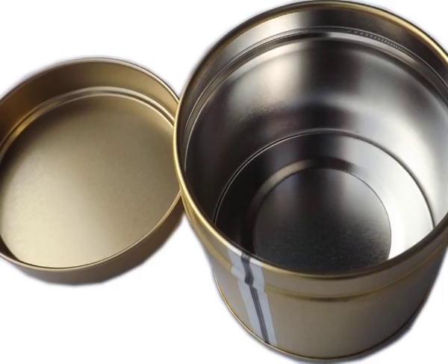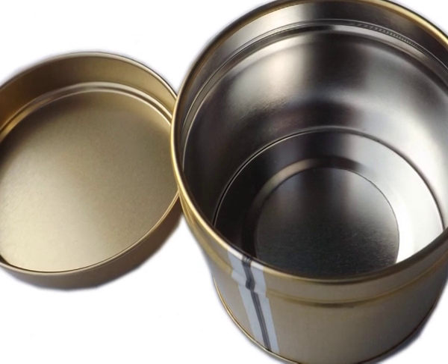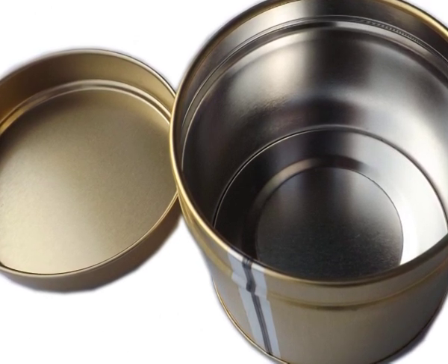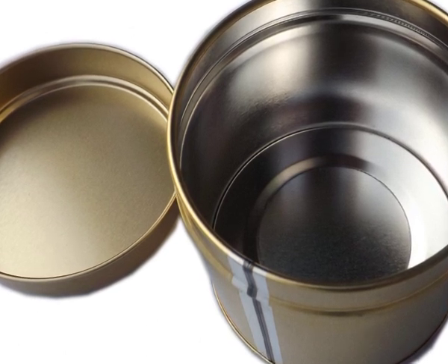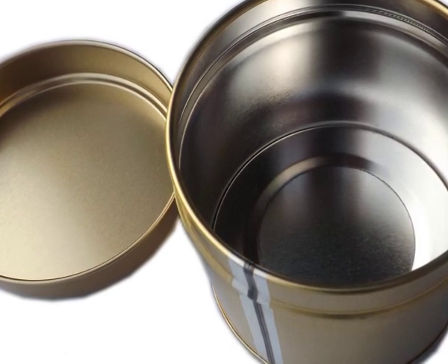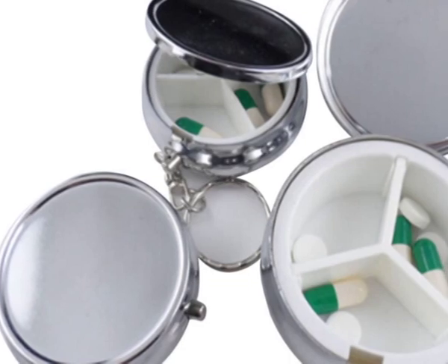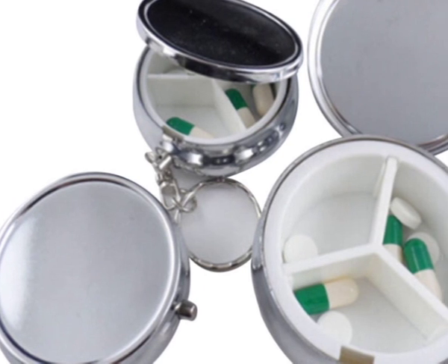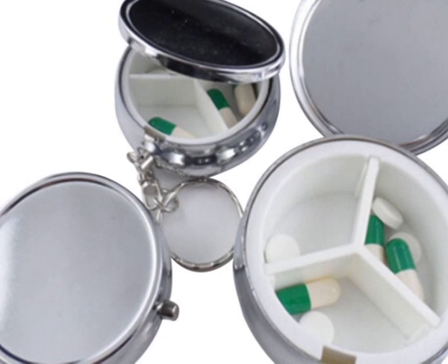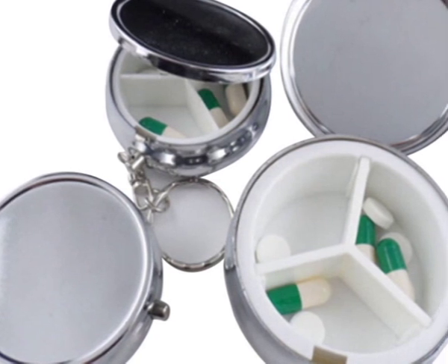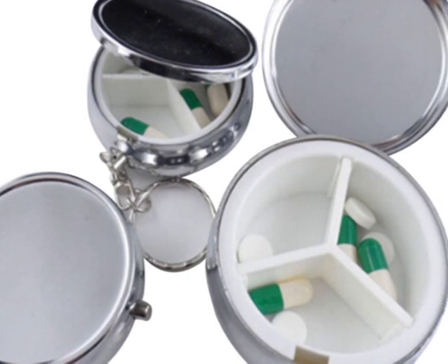Testing. An effective way of determining the suitability or otherwise of lacquered aluminum containers is by subjecting a sufficient number of filled specimens to shelf-life tests at varying temperatures, and by extracting specimens at regular periods and examining the product and product aqueous contact area visually and by means of a surface microscope.